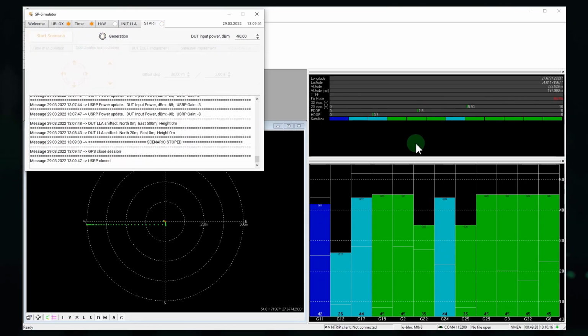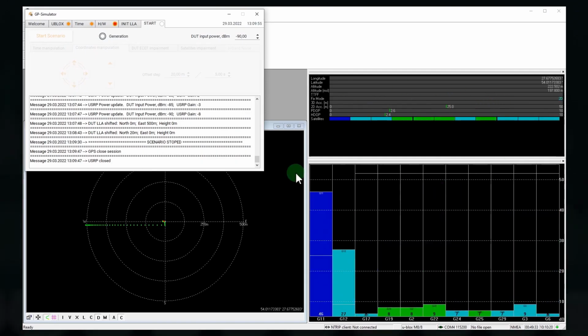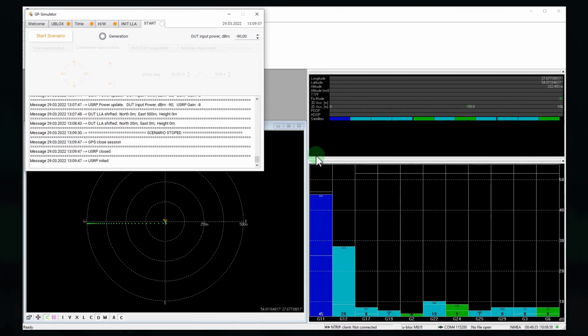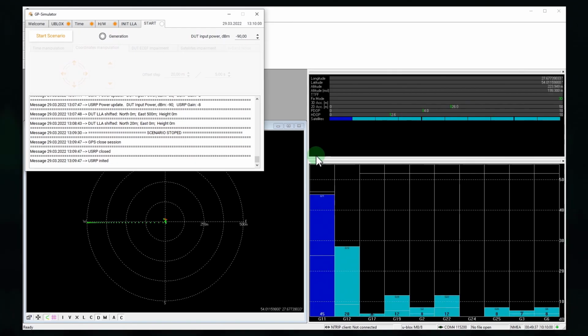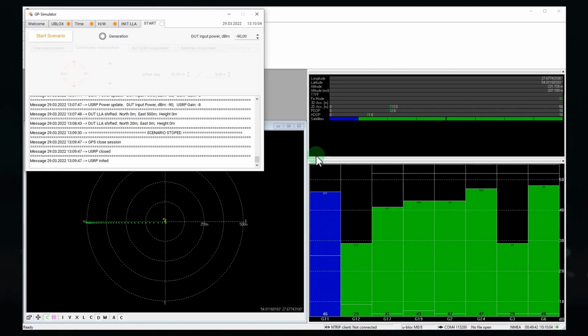You can see here that the receiver has lost fake signal tracking and is trying to find a new one. It's going to take some time. Let's wait. Finally it works. As you have seen, with the non-coherent attack, we needed to generate huge power to block the original signals. The receiver under test malfunctioned at the beginning and at the end of the attack. Satellites were blinking, there was a loss of tracking.